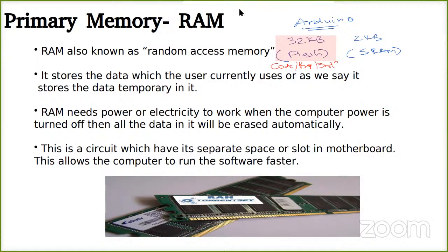What is going to be stored inside your SRAM? In the SRAM you are going to store your variables, the values of variables, etc. I hope this is clear. You only have 2 kilobytes of RAM. So if you have hundreds of variables, then your RAM will be used up, and your program will not execute the way it should. This should be clearer when we are actually doing Arduino.